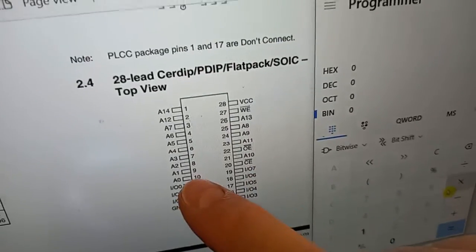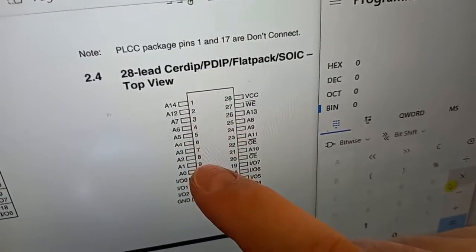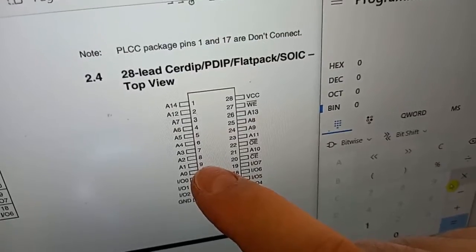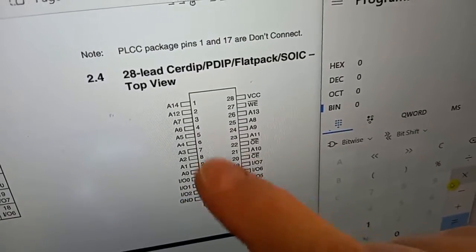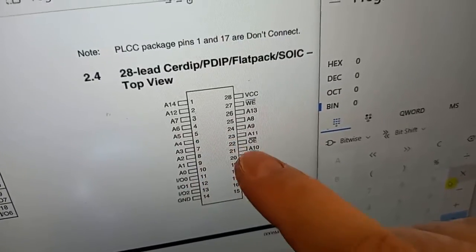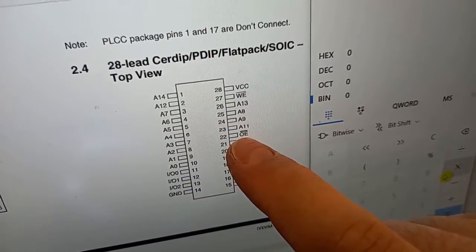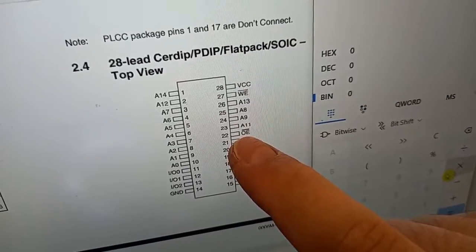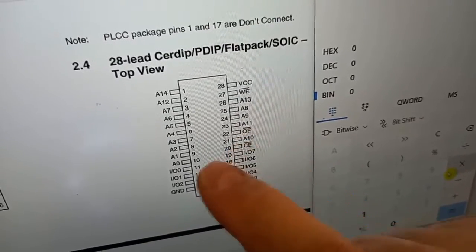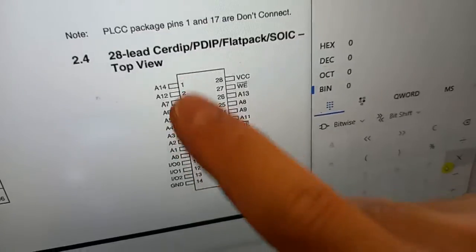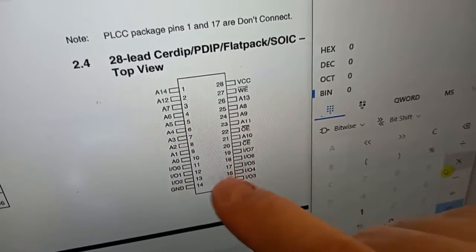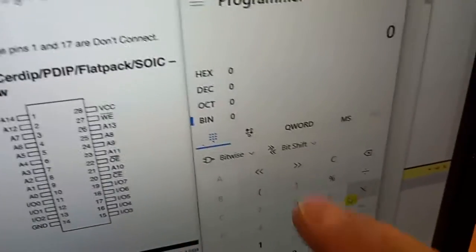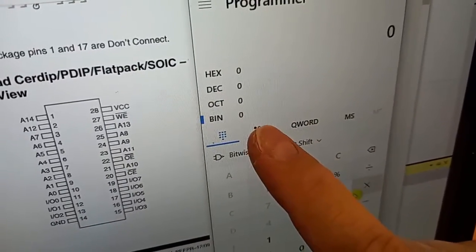So it's like a book. Every page has a number starting from 0. That is address 0. It has some information sitting inside, and this pin is output enable. When we enable the output by pulling this pin low, then we will get the content of this address. For example, page number 0 will show up here at the data bus. And we have address number 0.